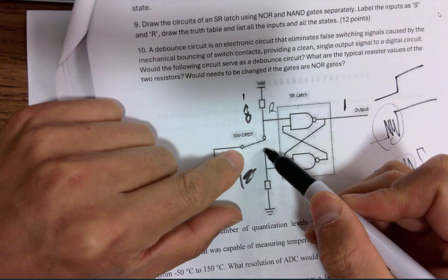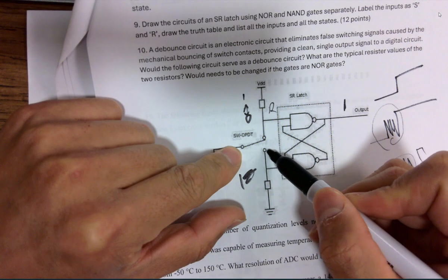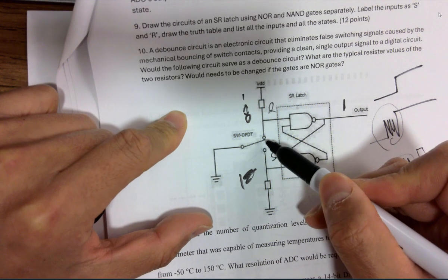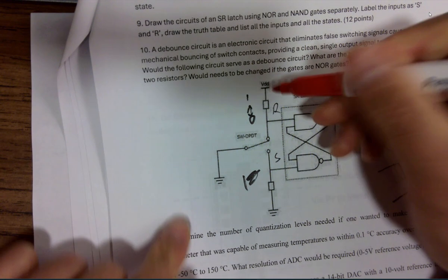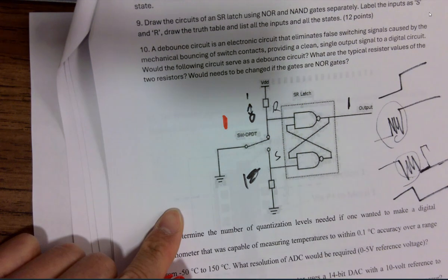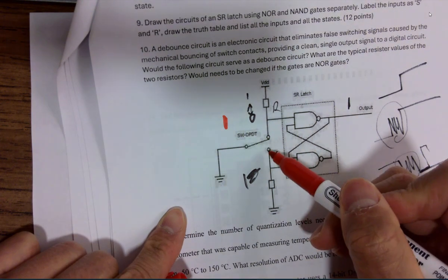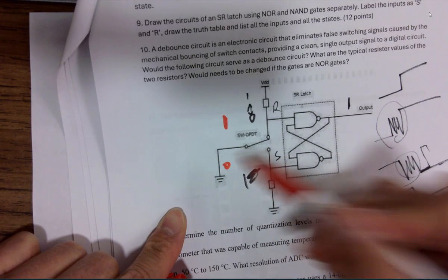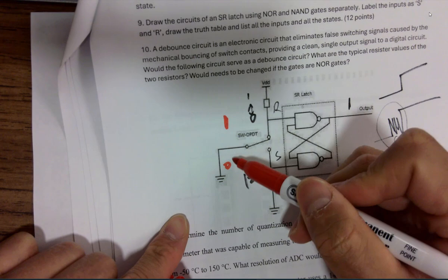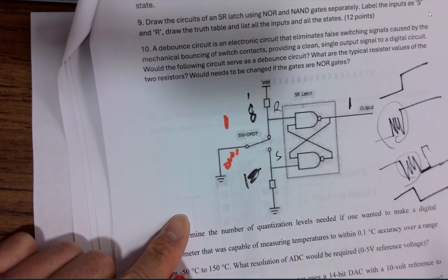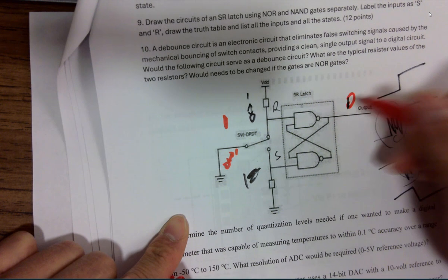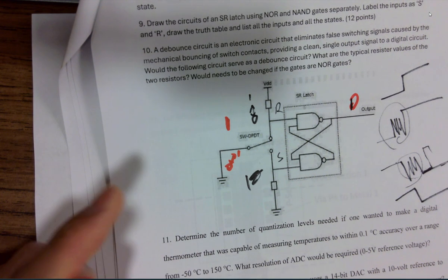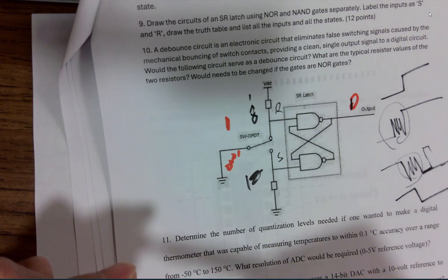Whenever this guy reaches it the first time, it's going to give a 0, right? And this one, after the vibration, becomes 1, because it's being put up. Once this guy touches it the first time, it should be a 0 first, before the vibration. And then there will be a vibration after that. So before the vibration, it's going to reset it, and the vibration won't change anything because of the memory. Make sense? So that's a debouncing circuit.